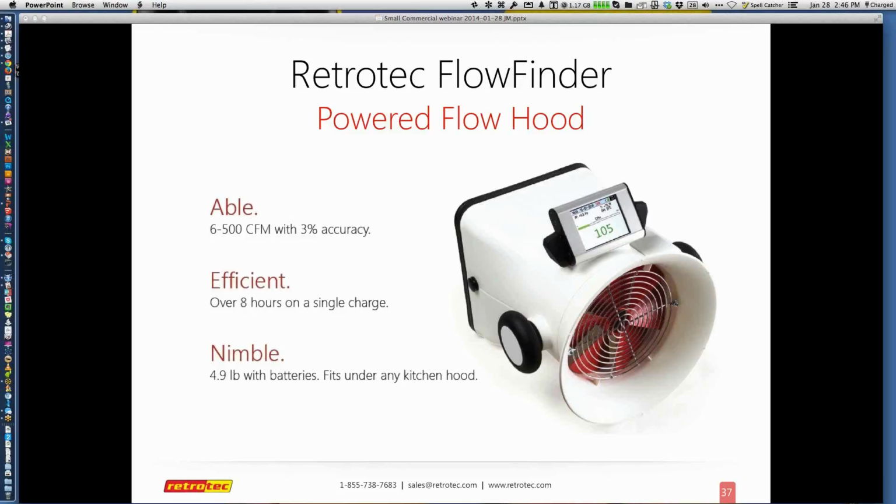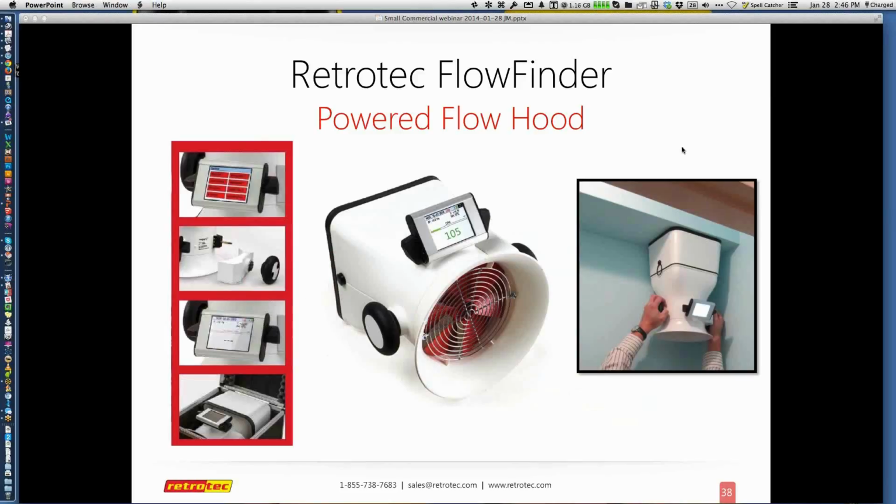The end fitting is 8.5 inches square with rounded off corners, and it's about 10.5 inches long. So this is an ideal device for measuring exhaust fans, kitchen stoves, range tops, and so on. They're notoriously hard to get at, and even if there are relatively big gaps that you can stick your hand around, because it has zero pressure sensing that goes right down to 1/100th of a Pascal, you can have some pretty big gaps around it and still get a very accurate reading. It's kind of uncanny how well it works, and it takes a reading in about 10 seconds.